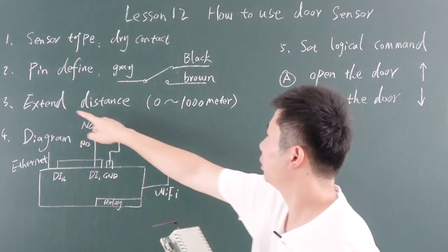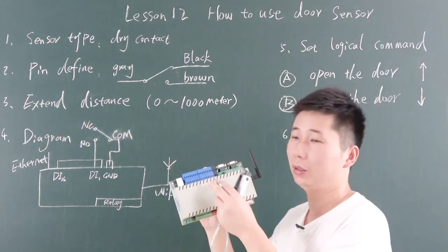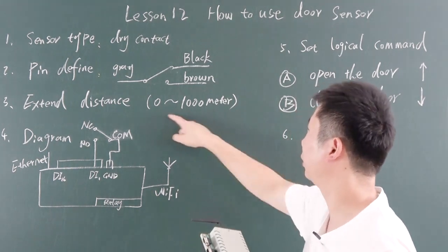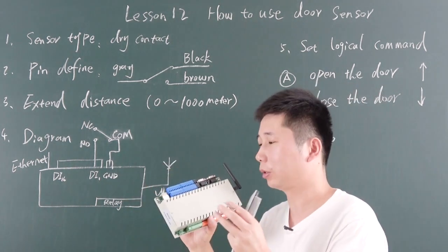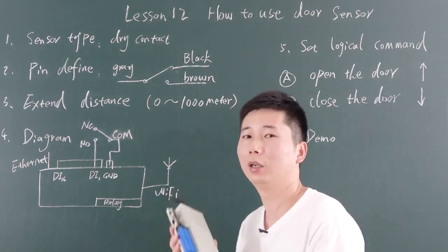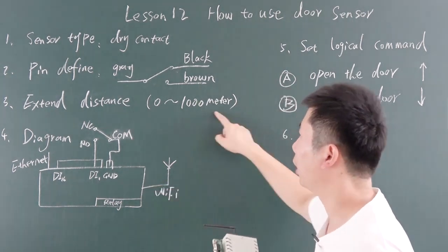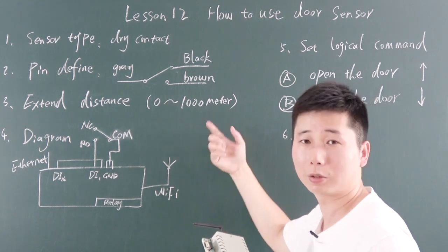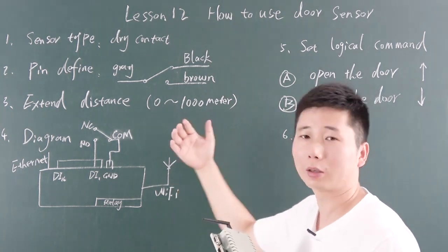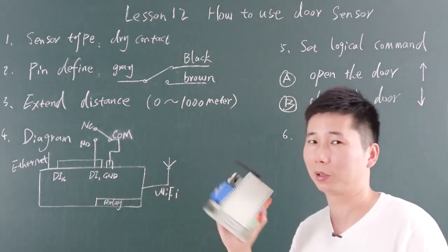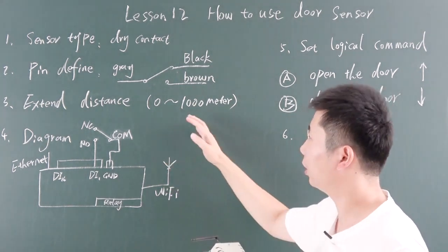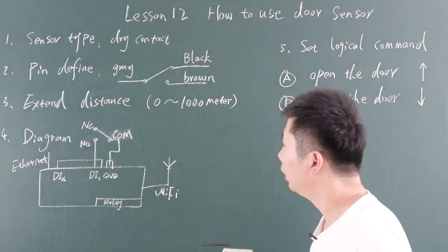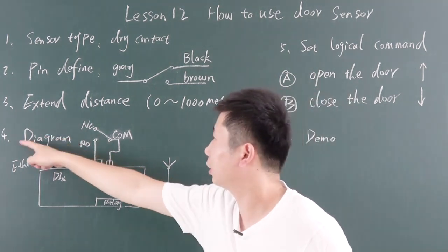We have designed this controller to support a maximum of 1 kilometer, with a long distance circuit inside. Only the digital input can be used for such a long distance. The analog and temperature sensor inputs will not reach so far, because this is the digital input.